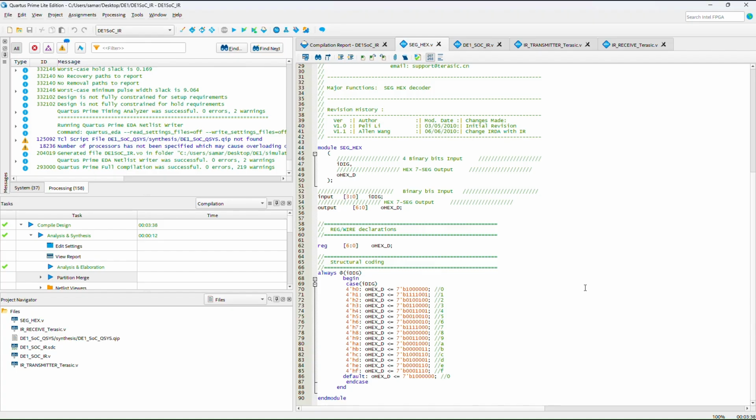As I mentioned in my earlier videos, a 7 segment display on a Terasic DE1 board is basically active low, which means that whenever you have a zero, that bit will be lit up. Accordingly, we have coded our data in hex, which means that each 7 segment display can display 4 bits. So 0000 to four ones would be 15. This is what you could display on each 7 segment display, and we have 6 of those. This will come in handy later on as we look deeper into the program.